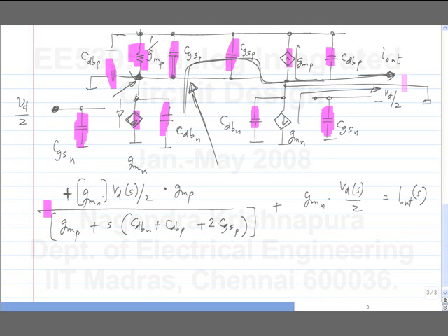But at very high frequencies, the contribution will be 0 because the current mirror is not mirroring anything. So, what should happen at DC? You will have some gain, which is the sum of this GMN and this GMN. Okay, and at very high frequencies, this part will go away and you will have only this. So, you should have half the gain at high frequencies.